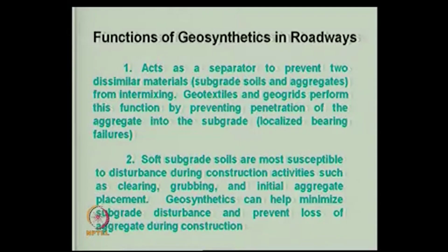In fact, during construction they are quite effective. In some places like soft soils, it is very difficult to clear them, and with initial aggregate placement, as I just mentioned in the other examples, if you try to put aggregate, it gets mixed up, and you may lose some 30% of the aggregate just to see that you have some hard material in the beginning. But if you have a geotextile, you know exactly the quantities of aggregate you have placed. That way the contractor would not claim that there is a loss of aggregate, and there is no problem here. So they help in the prevention of loss of aggregate.